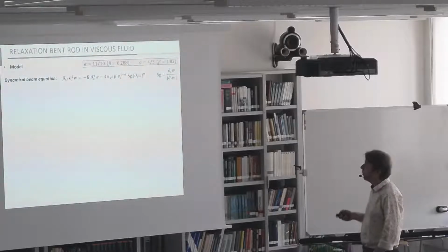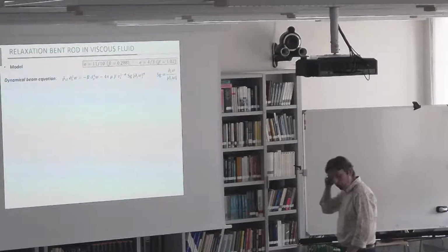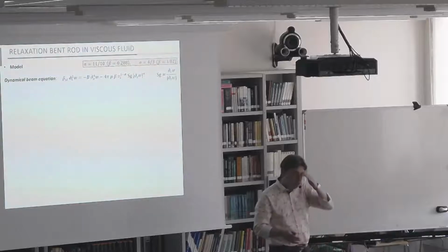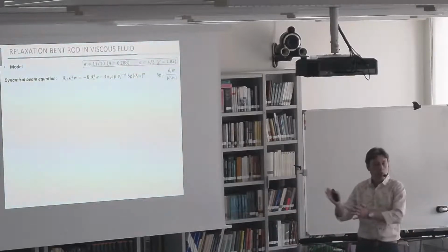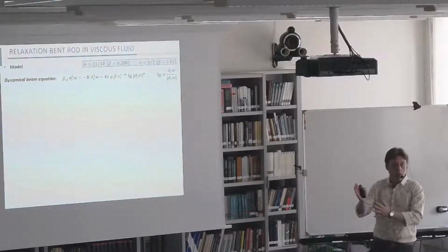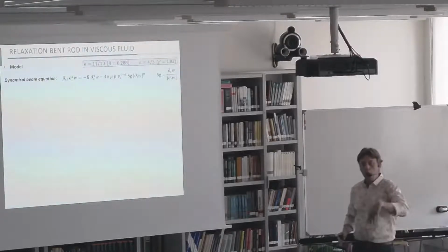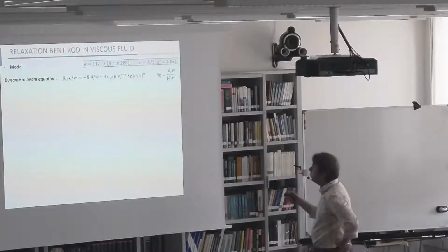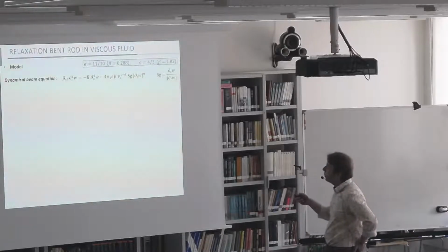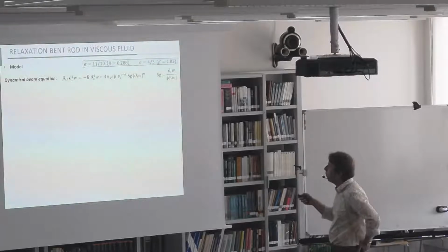So the viscous force is here. Notice that I have replaced the velocities by the absolute value of the velocities because when it's computed with a cylinder, the velocity always has a given sign. But when you oscillate, the sign of the velocity changes. So you put the absolute value and you take into account the sign of the velocity here in front of it.